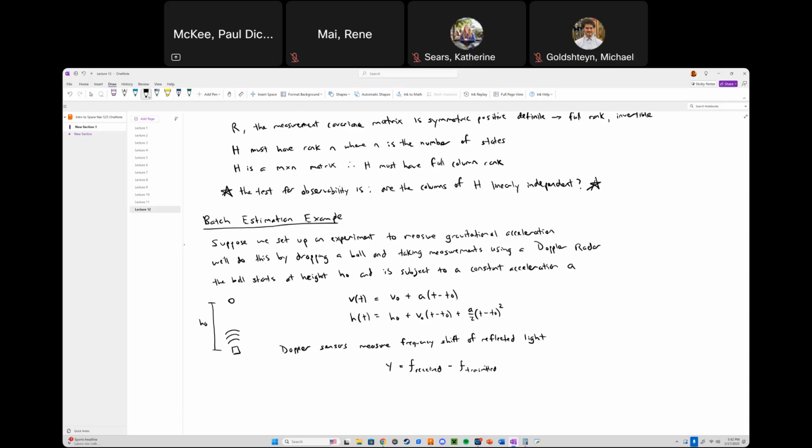So it's going to send out a signal, it's going to receive something, and it's going to measure this delta F, which is approximately -2 times the transmitted frequency divided by the speed of light, times velocity. So we will assume a transmission frequency. I'm going to put numbers to this. Transmission frequency of 35.5 gigahertz. And we will say that the speed of light is 3 times 10 to the 8 meters per second. I know it's not exactly that. It's close enough for this class.